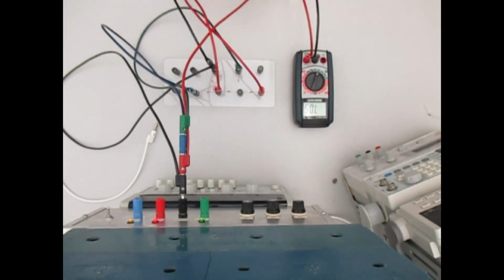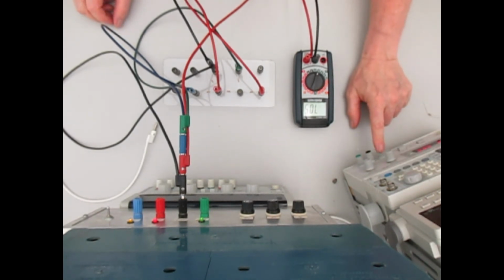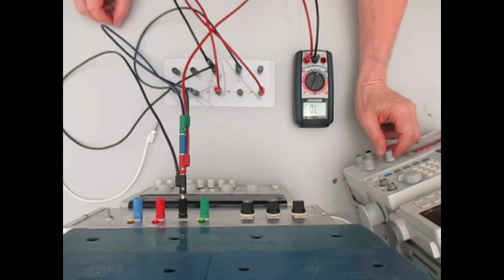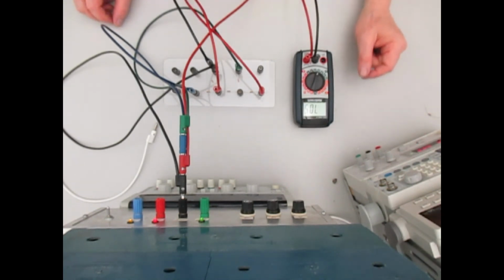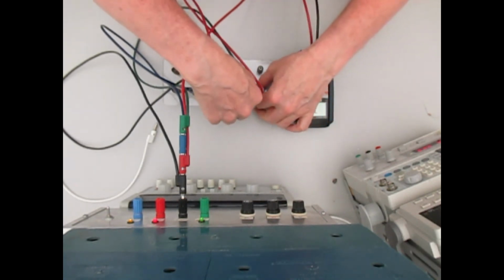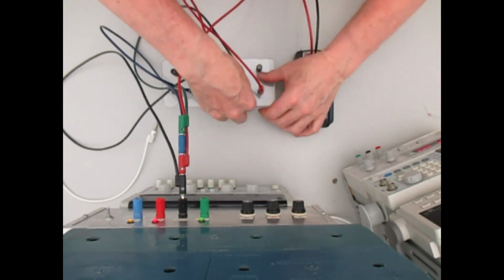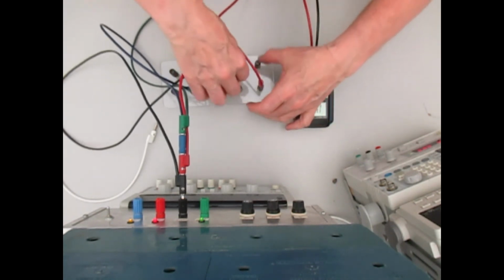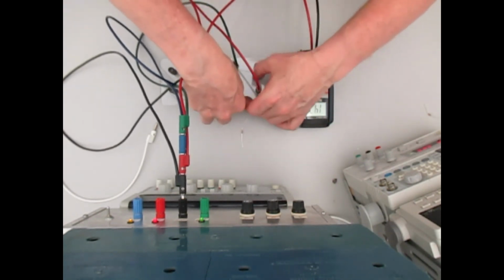Okay, so in our case, remember that we have resistor tolerances and things like that. When I build my circuit, I'm going to use a variable power supply and set it for 0.6 volts. And I'm going to say that the 680 ohm resistor is close enough to 705 ohms. And then we use, again, our 470 ohm for our R Thevenin.